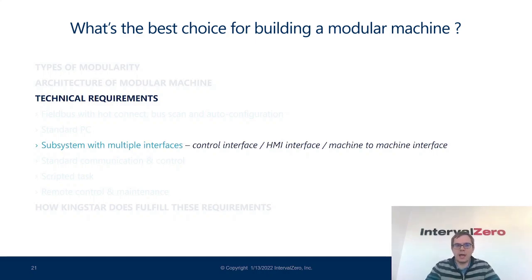Some of the main modules you will have are going to be the machine, the hardware abstraction layer connected to the field bus. Then you will have the machine interface for machine-to-machine, machine-to-factory communication. You will have a human interface, which will usually be the main controller, the main interface to select, to stop the machine, and to do operations. All of these, some need real-time, some do not. They need to communicate and to be loaded depending on the hardware. So the subsystem component is like the software platform that will allow all these pieces to interact.